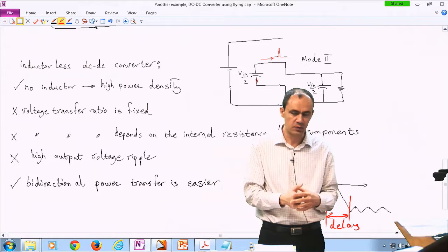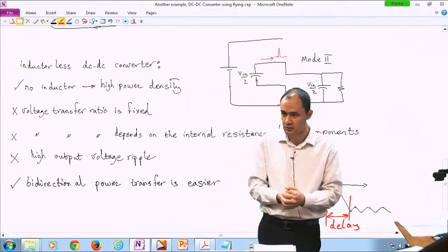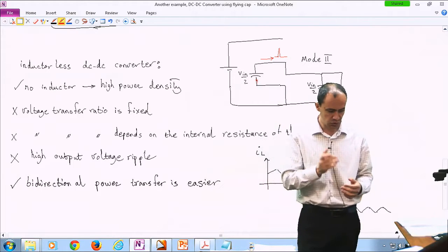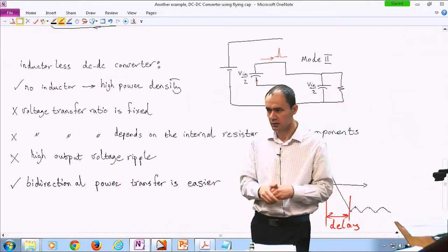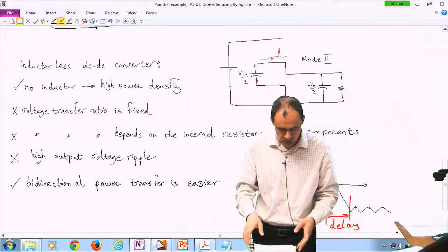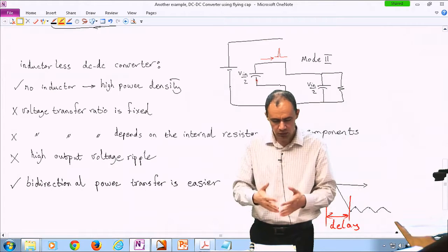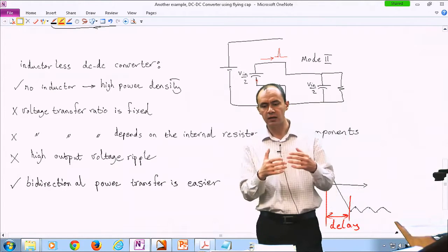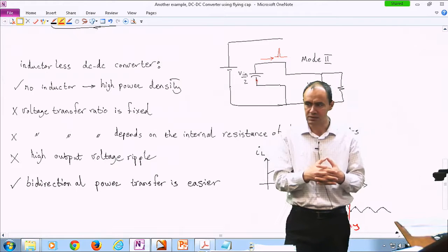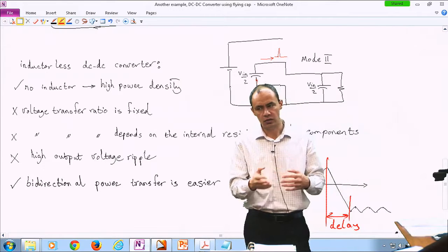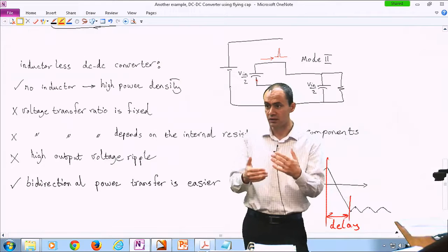Or you have an electromagnetic suspension system, which consumes a huge amount of energy in a short period of time once you hit a bump on the road. So in those applications, you can argue that if we had a 36-volt battery in our vehicle, then the losses would be smaller than having everything based on 12.